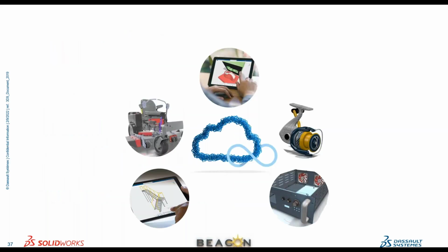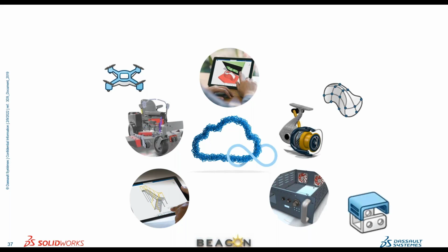So till now what we have seen is complete CAD on cloud, how you can do all the designing on cloud, which basically includes parametric modeling using 3D Creator, subdivisional modeling using 3D Sculptor, then parametric sheet metal capabilities on cloud using a browser on the 3D Sheet Metal Creator, and complete structure modeling capabilities providing you BOM, cut list, and exact lengths for developing your structures using the 3D Structure Creator. And for the tooling industry, you have Mold Creator giving you extensive automated mold capabilities, creation of core cavity and inserts automatically, and accessing everything from cloud.